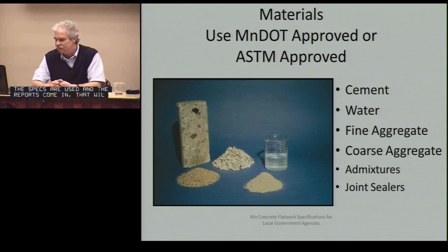But the idea is to use the DOT system or an ASTM-approved system. Aggregate people build aggregate piles for ASTM, I'm sorry, that's American Society of Testing Materials specifications, as well as piles for the local Minnesota DOT specifications. But a lot of the private work in the Twin Cities, our new Viking Stadium probably, the library, things of that nature, the light rail, they use some ASTM specification piles. So we opened the specification up that they could use those piles in this work as long as the pounds and the gradations and everything are in tolerance, or they can use the DOT-approved piles.